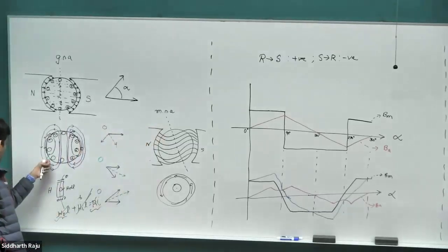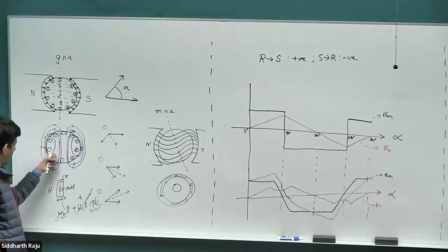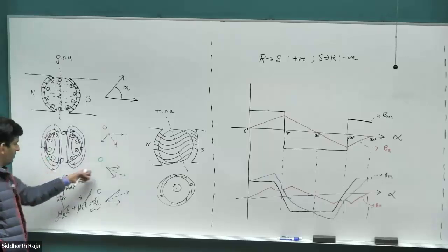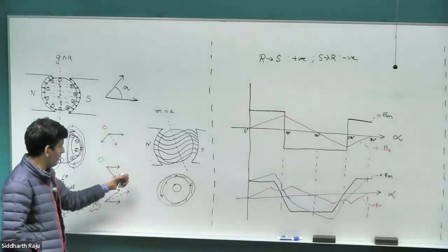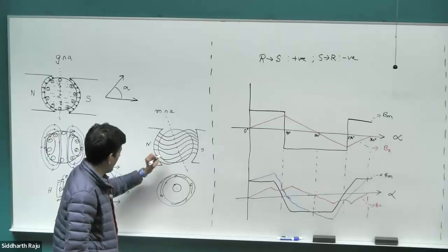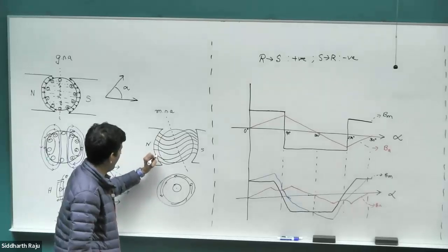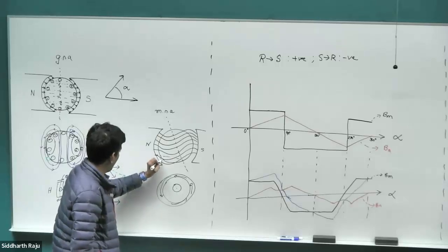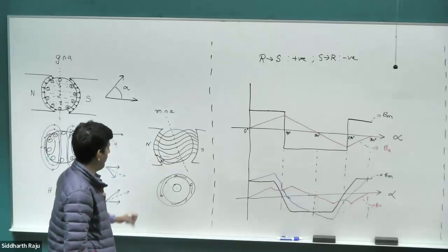And then if you look at this case on the bottom here, again, we have magnetic field which is going into the rotor, and we have magnetic field due to the current carrying conductor, which is downwards, which is effectively pulling it downwards. What would have been, if it was only the magnet and no current on the rotor, the magnetic field line would have gone like this. But now, because of this current carrying conductor having a component downwards, it's pulling the magnetic field downwards.